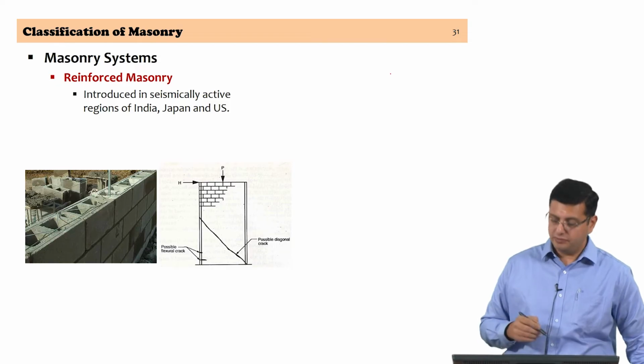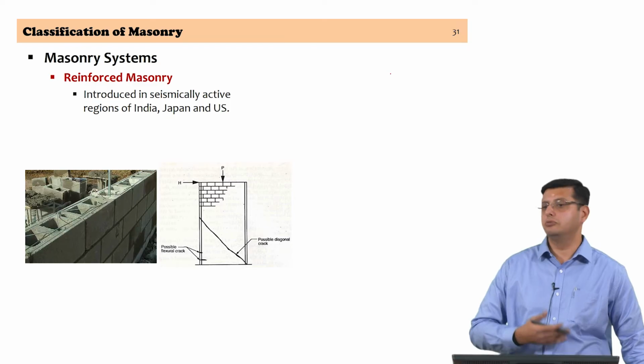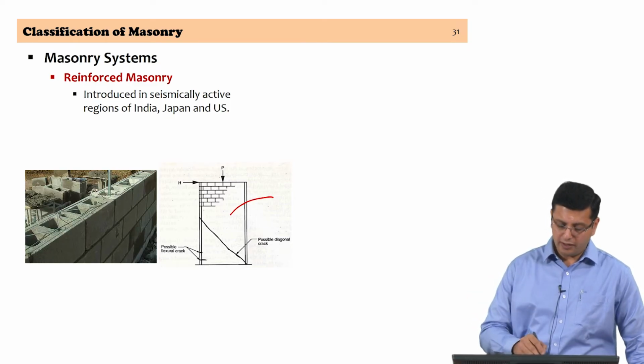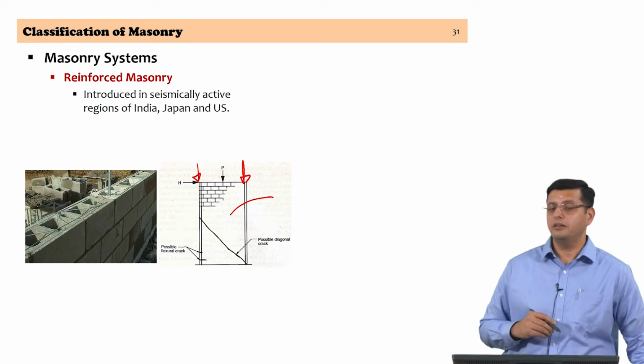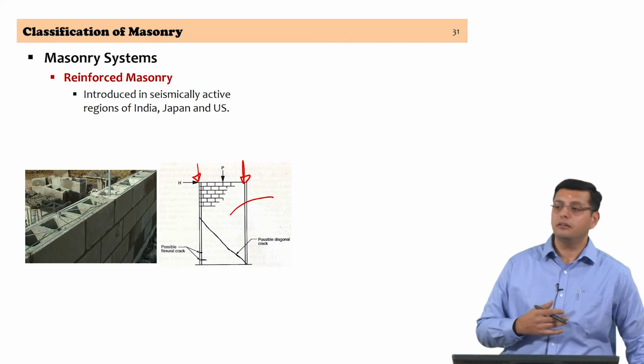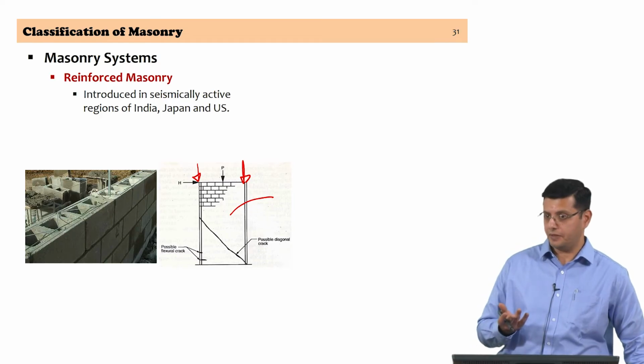So, if you have a reinforced masonry wall subjected to lateral forces, you have the masonry part of the wall, and then you have the reinforcement sitting within the wall. This reinforcement starts acting when the masonry starts cracking, right.